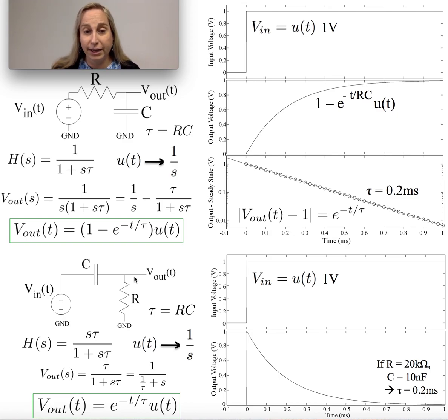It has to follow immediately, and the R can't slow that process down. So I get this immediate jump, and then it curls down from there. All right, so this works out well. And you kind of see this sort of exponential decay all the way down. And you could imagine if I have particular types of R and C, I could imagine getting this time constant, which I actually can extract out of being 0.2 microseconds.